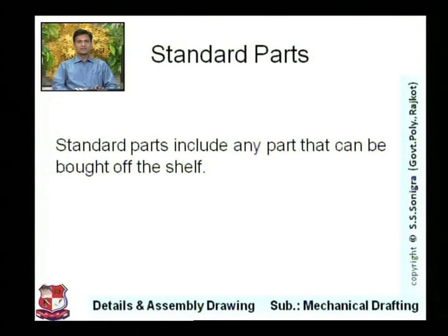In designing, suppose the diameter of the bolt we need to use is 29 mm, we will not write an M29 bolt, we will use an M30 bolt because an M30 bolt is readily available in the market. Standard parts do not need to be drawn.